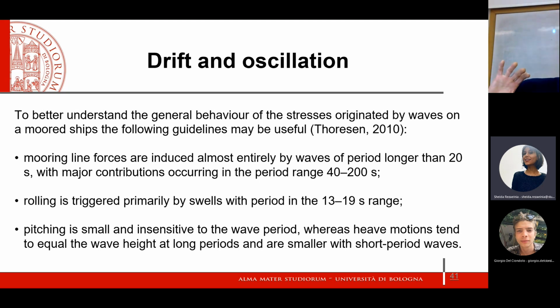Keep in mind also that ships have their own frequency of oscillation. Of course, a large ship oscillates with a longer period, with a lower frequency, and therefore it's more sensitive to waves with longer period.